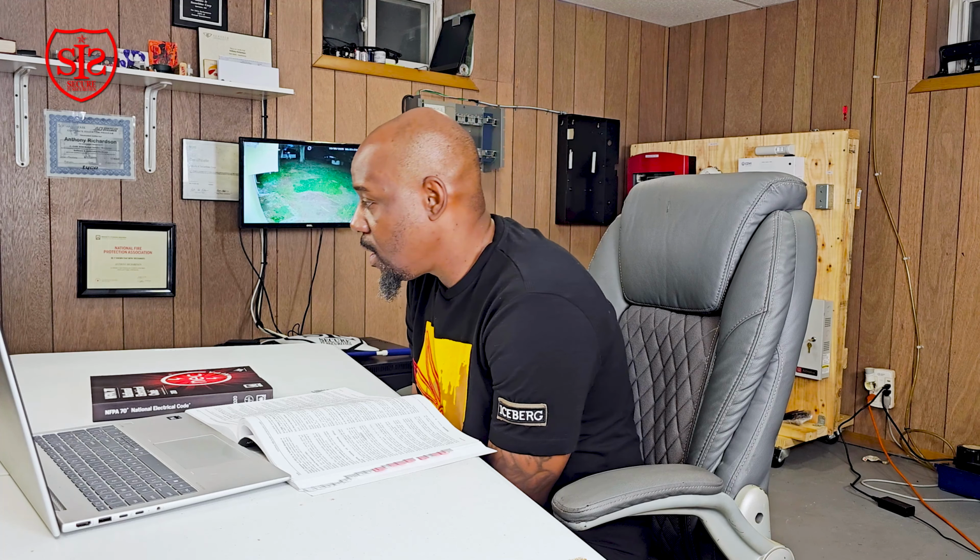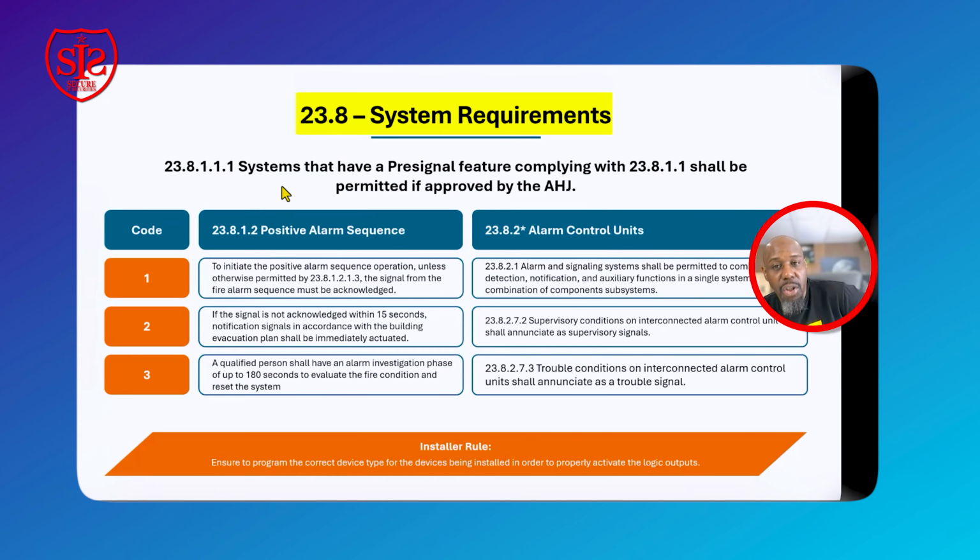This is a voice system. So this is a design for a voice system: floor above, floor below, and there's a fire floor. If the fire alarm is going off for 15 minutes, then the evac tone throughout the rest of the building will now sound. So now we are alerting the whole entire building that there may be an issue on one of these 3 floors.